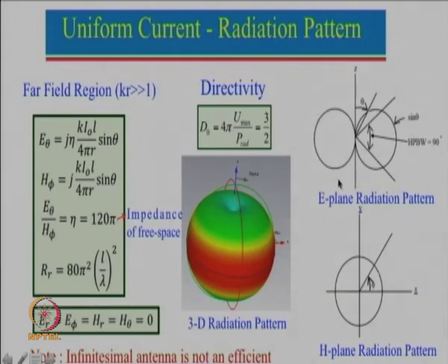However, this is just one plane that we are showing. For the H plane pattern, you can also think about a current carrying conductor placed in the z direction. So, where will be the magnetic field? The magnetic field will be given by these fingers here. So, this is the electric dipole antenna current, and the magnetic field will be like this.